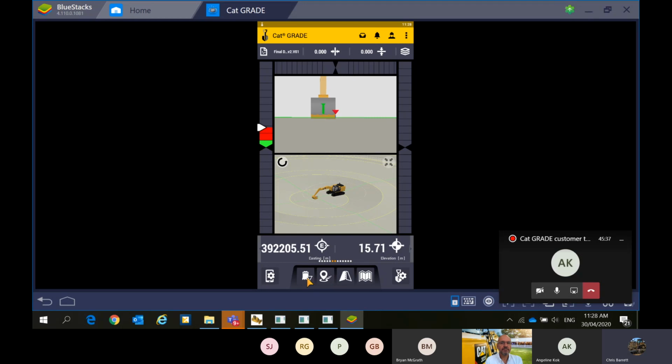Being a 3D machine, we like to roll that bucket into three different positions on that point, and also tram the machine and reach back if you're on an excavator, and make sure that point's still accurate within a few positions. Once you've done that, you can get into the work.